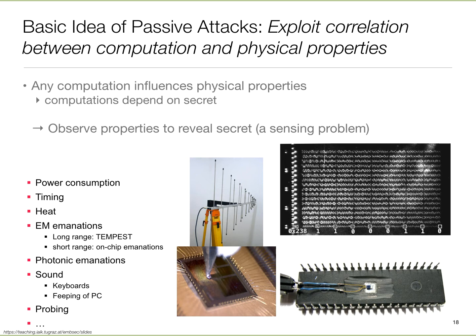More common, or at least more easily doable, are the passive attacks, where we are not allowed to manipulate the physical device in any meaningful way. We are allowed to observe the physical emanations, and just from those observations, we try to extract information. What we make use of is known physics, that is, how doing computation affects the physical properties. The physical property which typically gets used is power consumption. As I've often mentioned, the amount of power the CPU is consuming depends upon a lot of factors, frequency and voltage for sure, but also specific instructions and things like that.